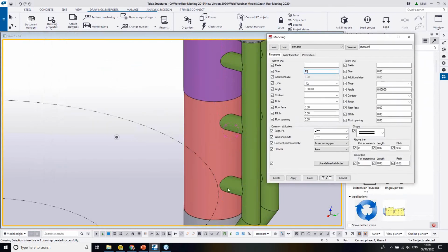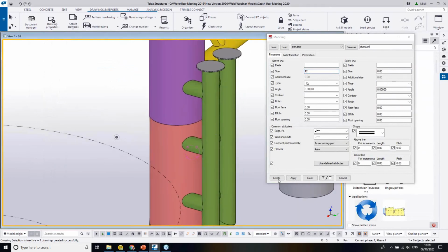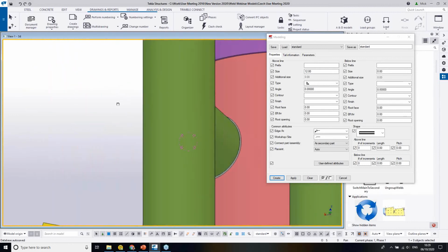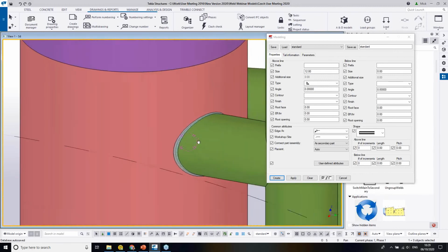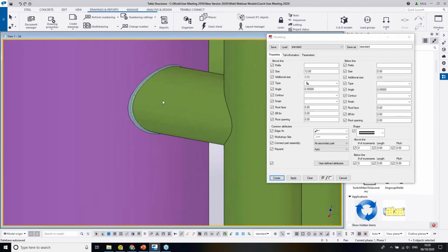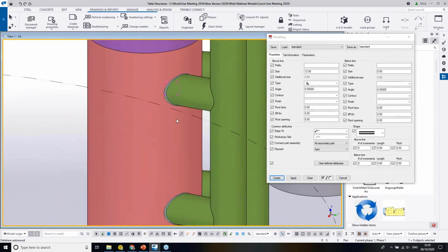What we do is I want all these pipes to connect to these different tubes. So you say create, and we'll say this pipe here and this pipe here, and then the middle mouse button, I'd like this one, and this one to connect to them. And you'll see, look, that it puts the correct welds around those pieces. So that means using this toolbox, you can automate applying the welds into the models.